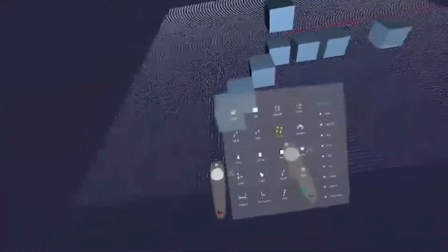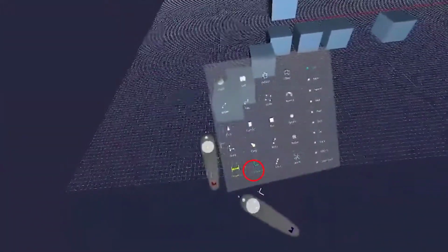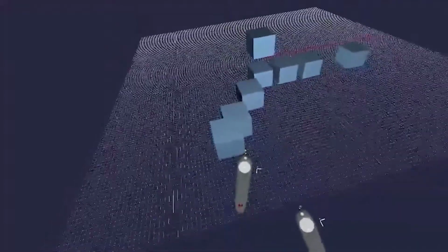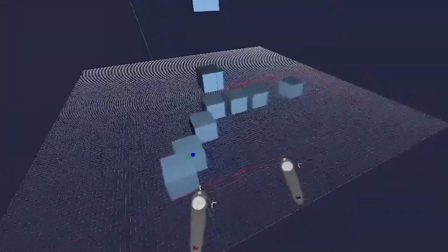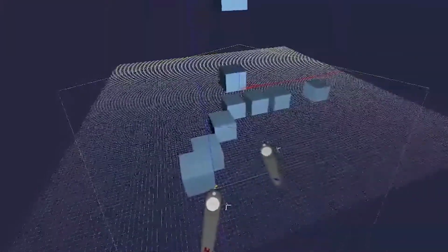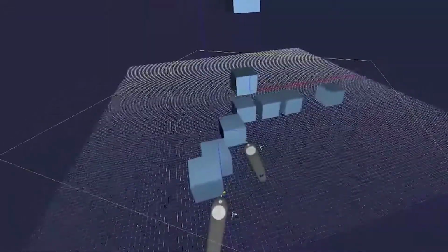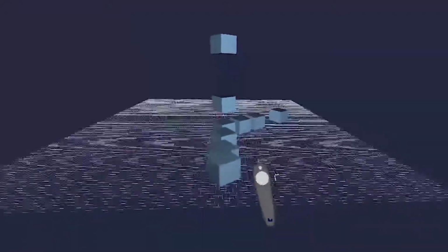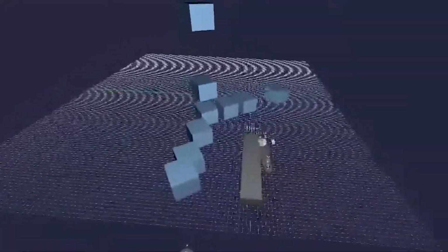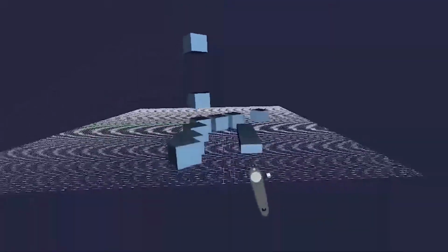So using the reference system command, I can select the bottom corner of the box, holding, I rotate the grid to the other corner of the same box in the diagonal, and notice the grid is now perfectly in the 45 diagonal I started with. So making new geometry, like a box in this case, will now be referenced to this new adjusted grid.